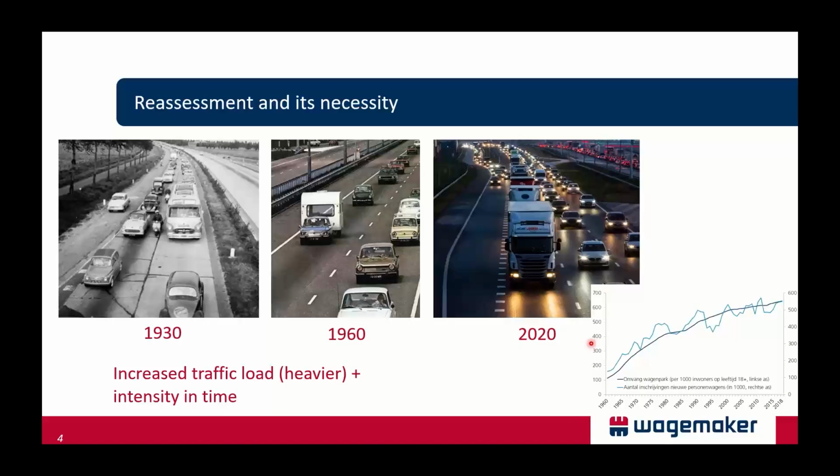Well, you can see that the traffic has become much more intense, and also the individual vehicles have become heavier. So this is, of course, an important reason for reassessment, because the loads on the structures have increased over time, and that is not the kind of loading they were originally designed for.